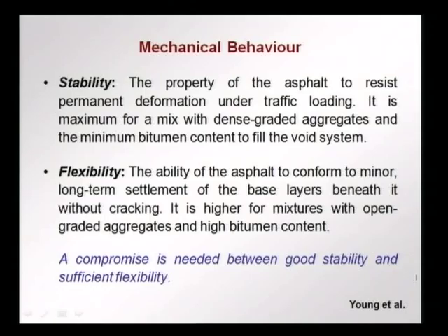We do not want a hollow space to form under the asphalt concrete, which will eventually lead to a depression on the asphalt concrete or a sudden cracking or failure. We want the pavement to be flexible to such settlement, and that is why asphalt concrete pavements are called flexible pavements.